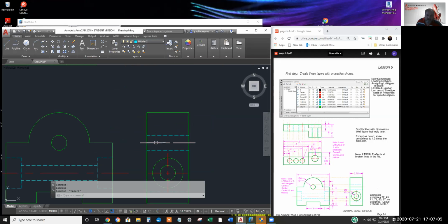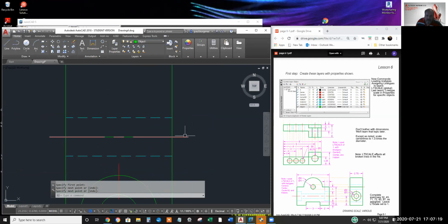I forgot the object line across here. I'll go to make current the object layer, draw a green line over the center. I'll erase the red line, go to any of the red colored layers, draw a slight whisker out.